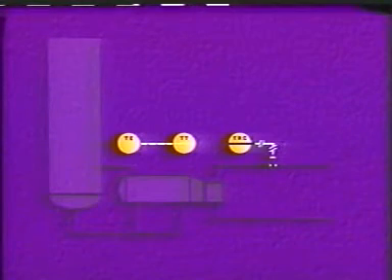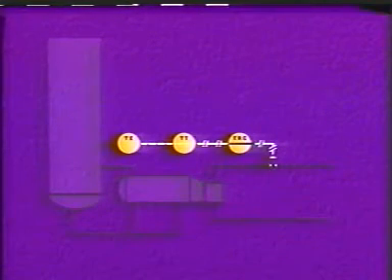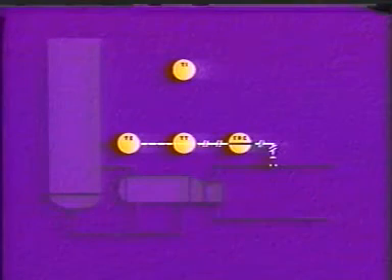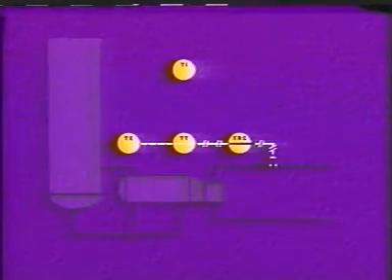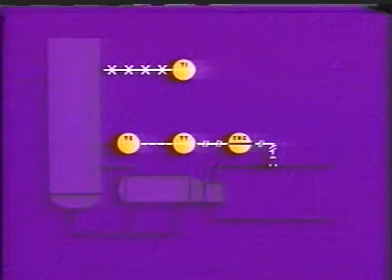These symbols show a thermocouple, the electrical wiring between the thermocouple and a transmitter, and a pneumatic airline from the transmitter to a controller. These symbols show a temperature indicator, an industrial thermometer connected to an indicating gauge. The gauge is connected to the thermometer by capillary tubing. In other words, a liquid or gas expands or contracts inside the tubing, and this indicates temperature. The capillary tubing is shown by a line crossed with a series of X's.